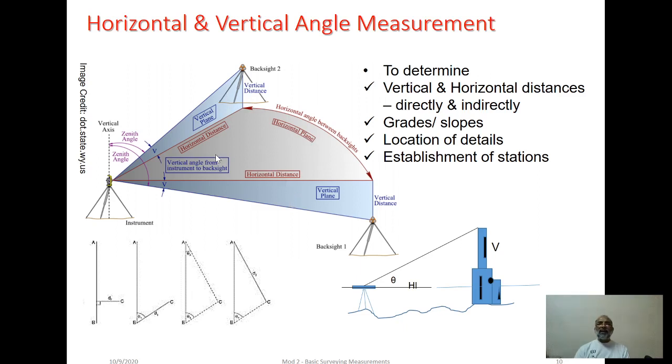Here, say, this is the position of the equipment. With respect to a certain line of sight, we are making the angle rightward up to the next reference line, and that is called the horizontal angle. Even as we consider the plane which is perpendicular to it, with respect to this horizontal plane, we are measuring the angle in the vertical plane up to this particular line of sight.